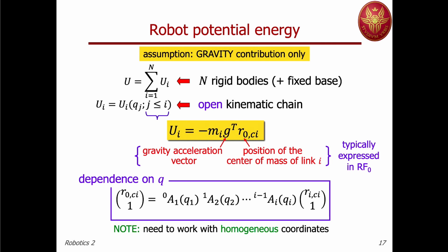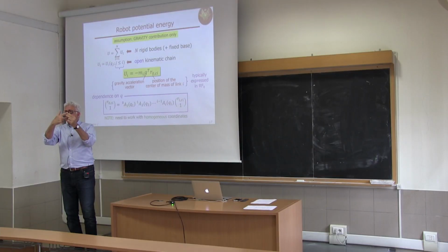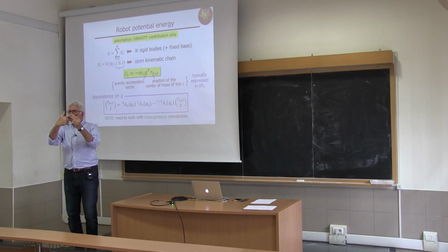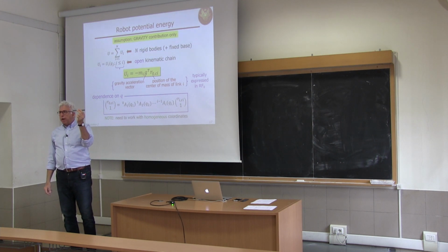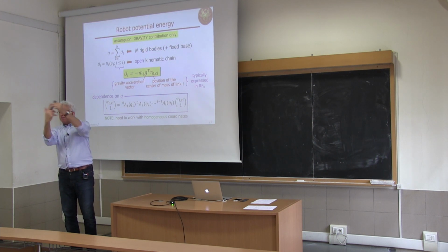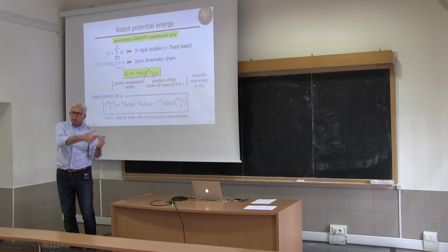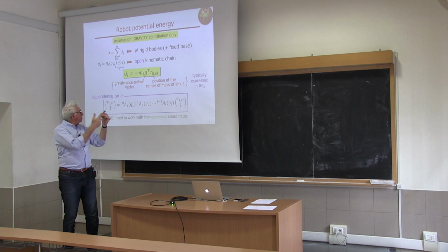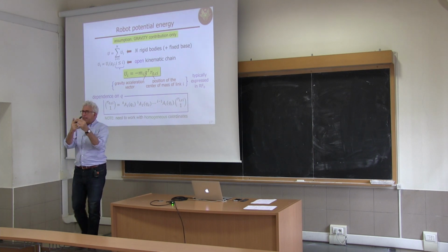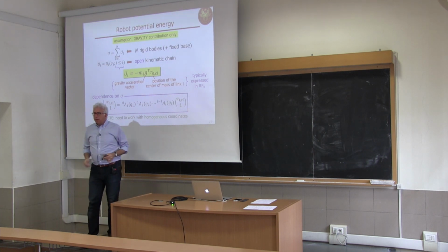This is a rigid body. If my frame i is attached somewhere, let's say at the corner, in this frame I can characterize the position of the center of mass in a unique way, and in this frame, even if the body is changing its orientation and position in space, the vector r_i,Ci expressed in frame i will remain constant.